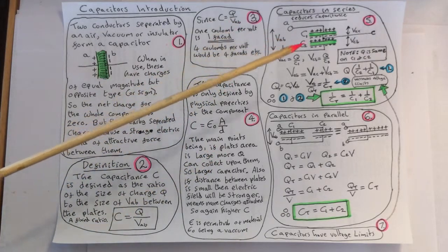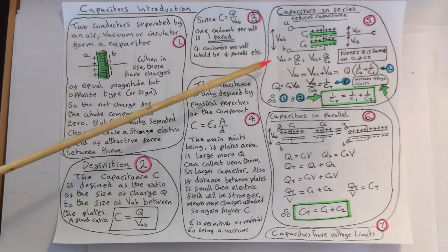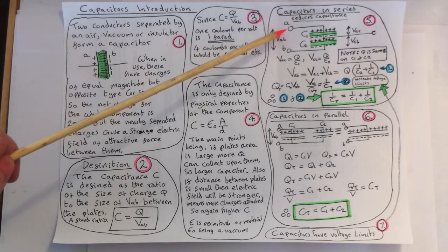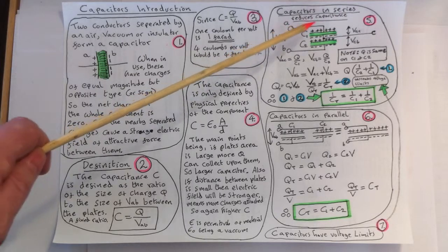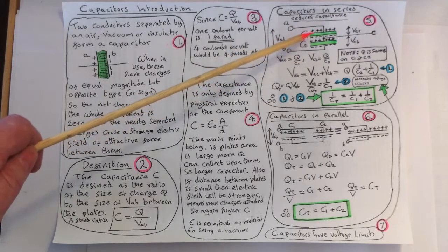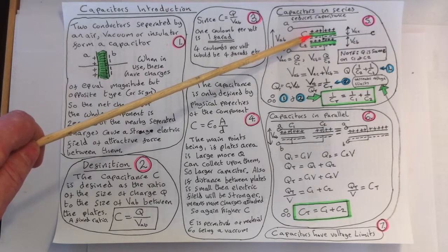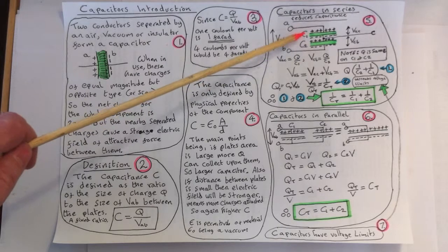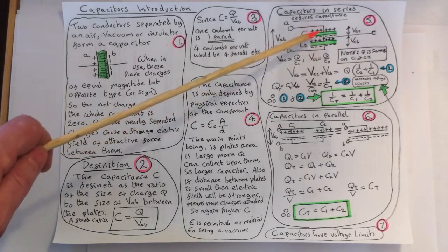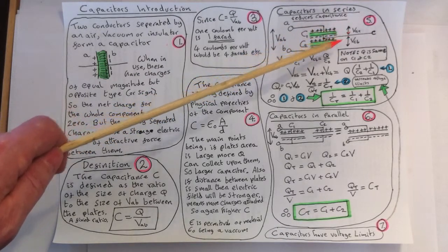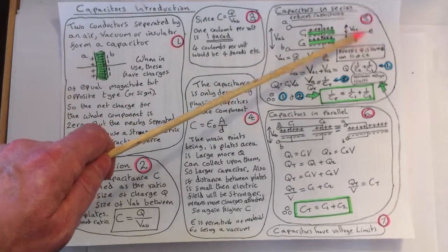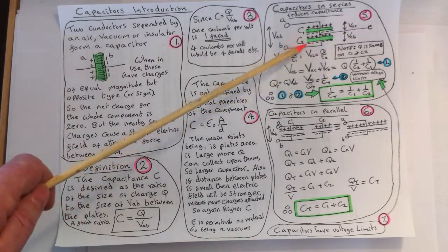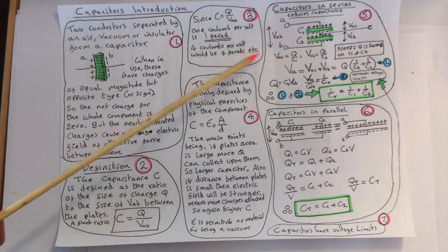So now, just quickly, this is something we can go through now. It's just working out the capacitors in series. I've got a very simple circuit here with 2 capacitors. The green here is representing the electric field between the plates, if you like. So there's 2 capacitors, C1 and C2. And between each capacitor there's a voltage, and I've labelled this middle section C. So we've got voltage AC and voltage AB, where this is B and this is A.